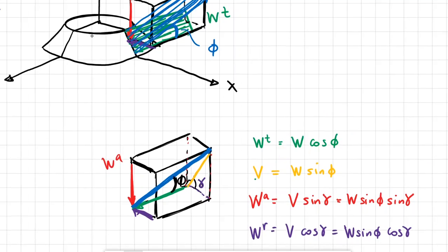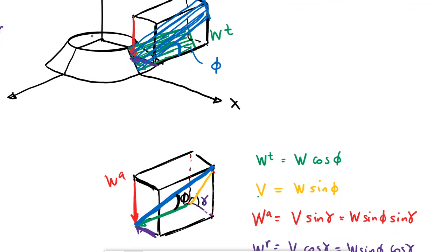So all I wanted for you to understand with the planes, with the distributed loads, is that it might not be super clear to some that the pressure angle is always between the distributed load that is tangential to the teeth or to the gear and the actual pressure, the angle at which the forces come. Okay.